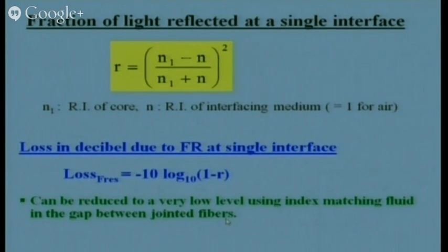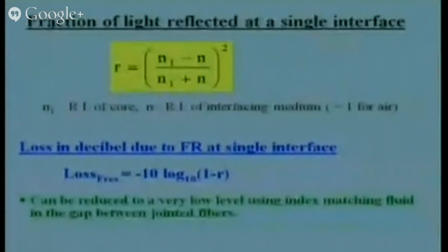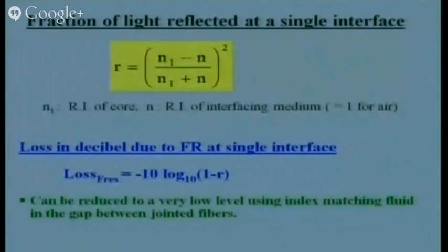So use the epoxy whose refractive index is very near to the refractive index of fiber. Normally with the fiber we use silica epoxy, silica resins, because fiber is silicon oxide, and epoxies are also silica epoxies. So it reduces the Fresnel reflection. So index matching gel can minimize the Fresnel reflection, but it will not be zero. So Fresnel reflection is one of the loss mechanisms.